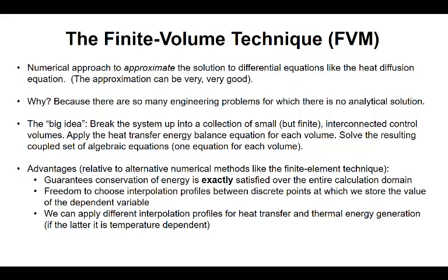Why should we learn a numerical technique? Because there are so many engineering problems for which there is no analytical solution. The big idea of the finite volume method is the following. Break up the physical system into a collection of small but finite interconnected control volumes.